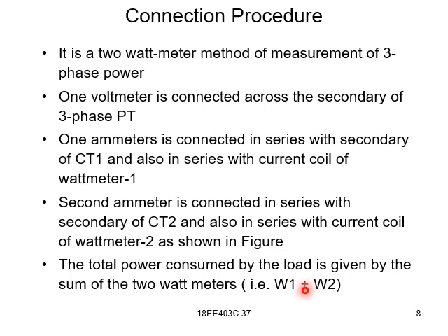So in the previous case, the connection was already shown and explained. Now we are explaining the connection procedure, and then we'll make the diagram. Actually, in order to measure three-phase power, we just require 2 wattmeters. 1 wattmeter is not sufficient. Actually, it requires 3, but 2 is more than enough.